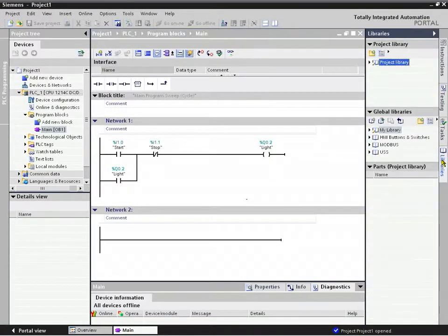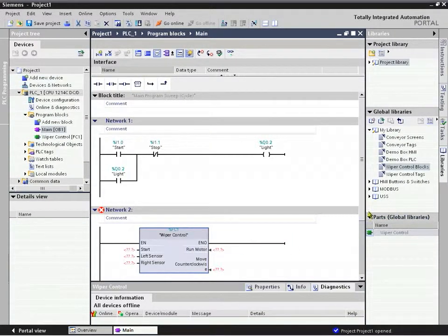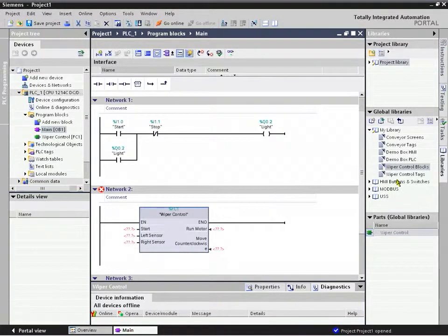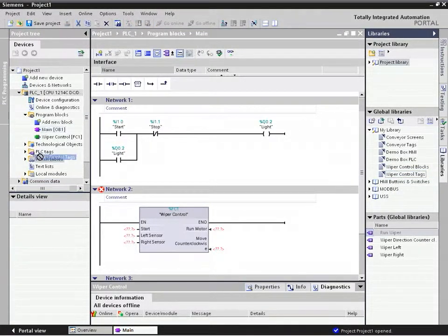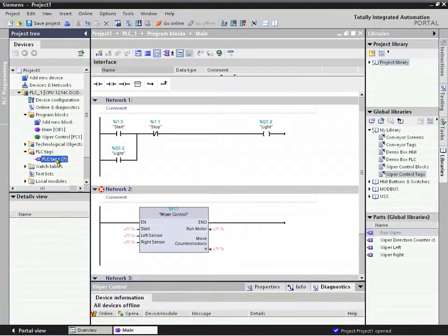We can go right over here to our libraries tab, and I've already pre-configured a library folder that has several portions of reusable code that someone quite often uses for their machine or their control systems. The idea is that we can simply drag in these blocks that are already proven, already tested logic, into any existing or new project, and then bring over their tags into the tag database for this project, and then simply parameterize this particular block. And this saves a lot of repeat programming.